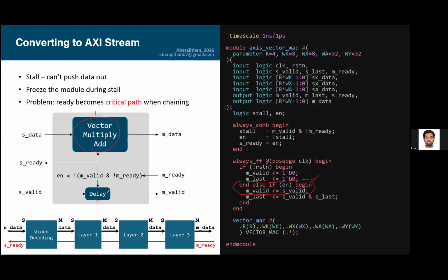So then the question is, what happens if you don't have a deterministic latency? I have some designs where you don't have a deterministic latency. Then you do this inside the module itself. In the module, you are calculating the output in a certain way, and as you calculate the output, you also calculate when it's going to be valid.